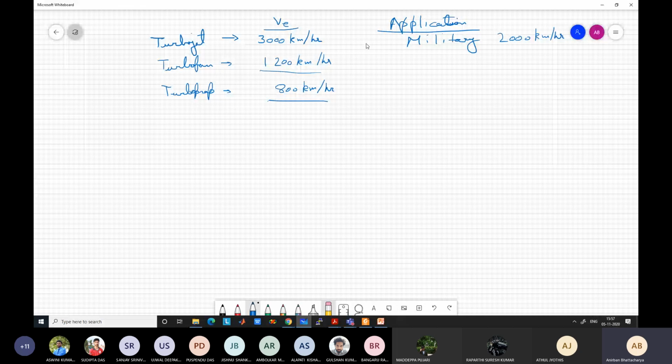For military aircraft, either turbojet or rocket engine. But a rocket engine is very inefficient because it needs a lot of mass, as it needs to carry its own oxidizer with it. So the only option left to us is the turbojet engine. We will come to ramjet and scramjet also, which can also be used, but their nature is similar. In those cases also the exhaust gas velocity is very high, and their propulsive efficiencies are also higher at very high velocity.